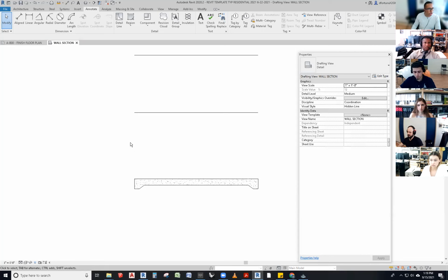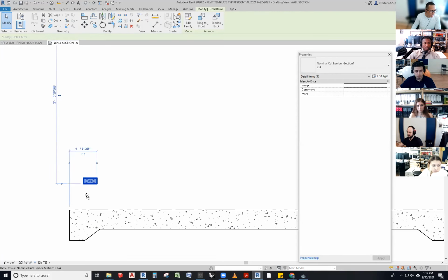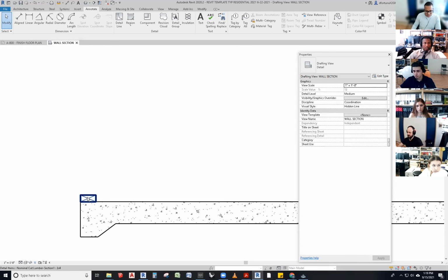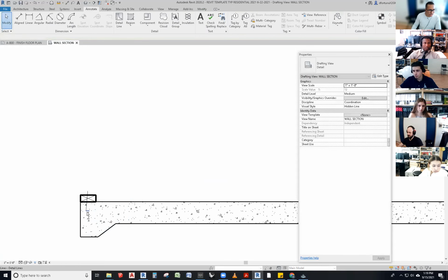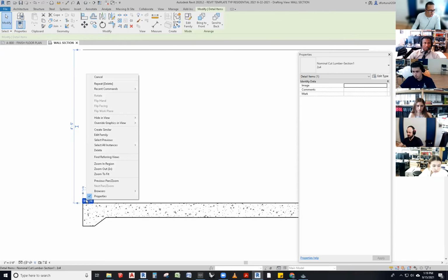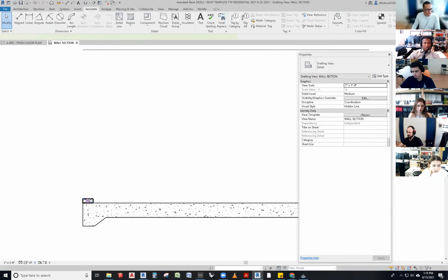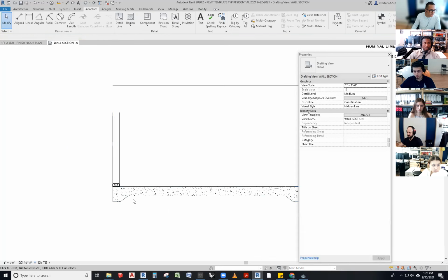Then how does this work? Well, if it's a finished basement, the next thing that you're gonna have is perhaps a 2 by 4 that's gonna frame that wall. Okay, and then this is a 2 by 4 plate that has to be pressure treated because it's connected to a concrete piece, right? And when you have a wood piece with concrete, it's got to be treated so that it doesn't rot, or at least takes longer to rot. But those then are going to have studs going about 16 inches on center from there, right? So that starts making sense right there.